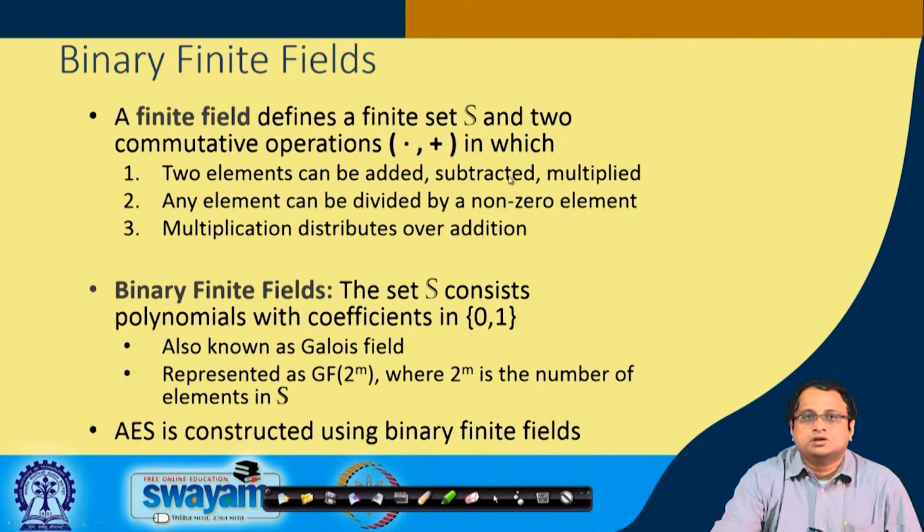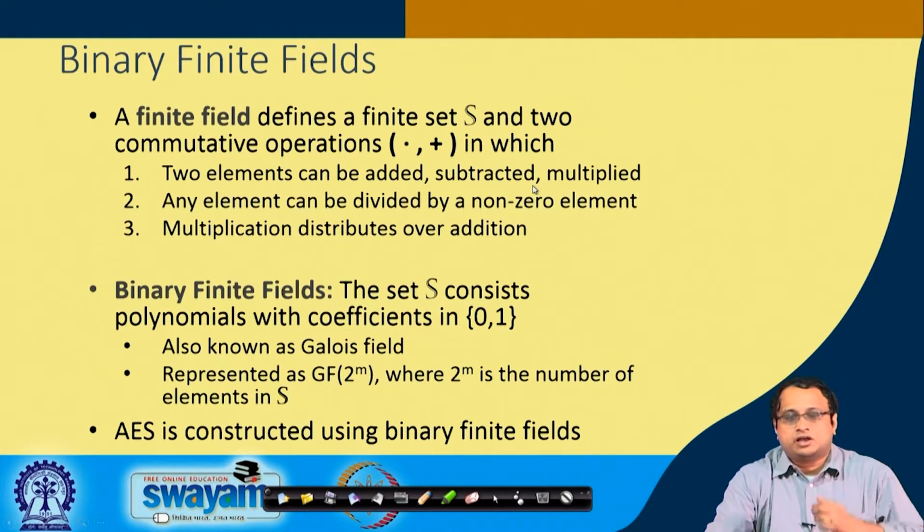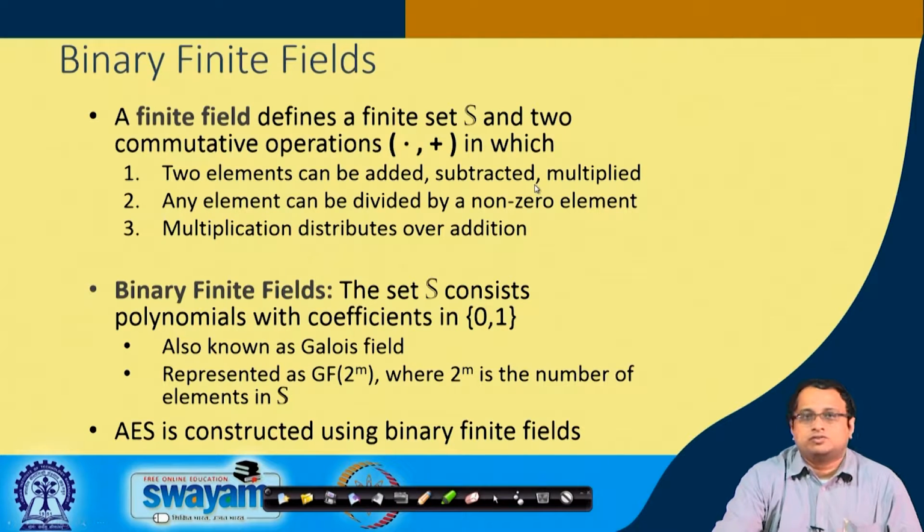As we have also studied in our previous discussions, when you have GF2 arithmetic, many of the underlying operations become efficient to implement. For example, GF2 based addition can be done only by exclusive ORs. Likewise, squaring was very easy to implement: you just needed to interpose zeros in between.